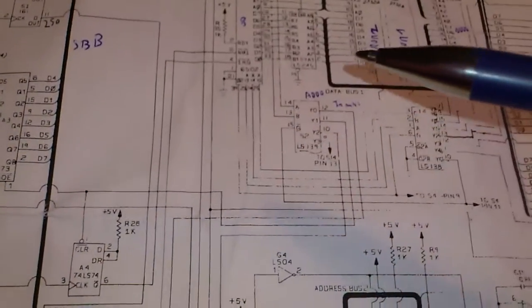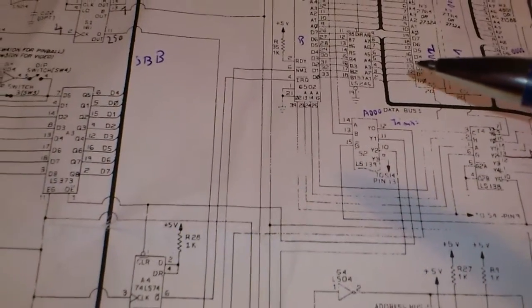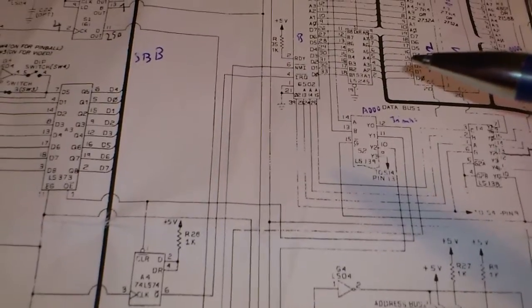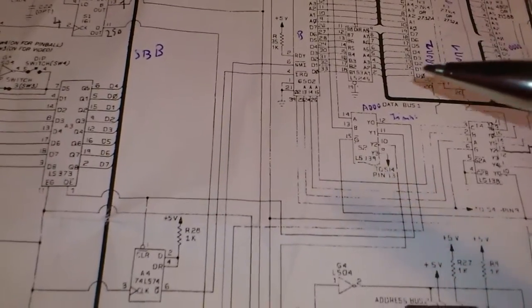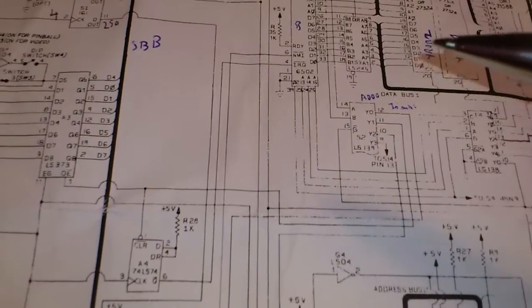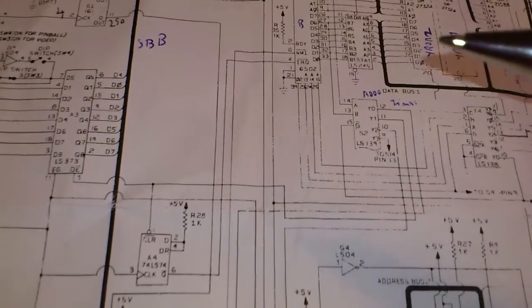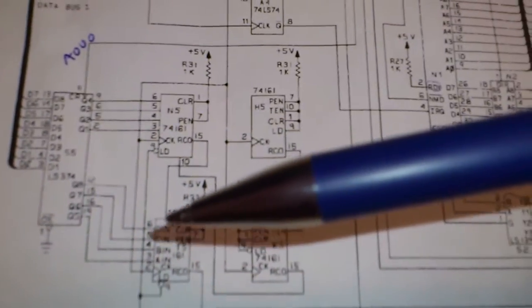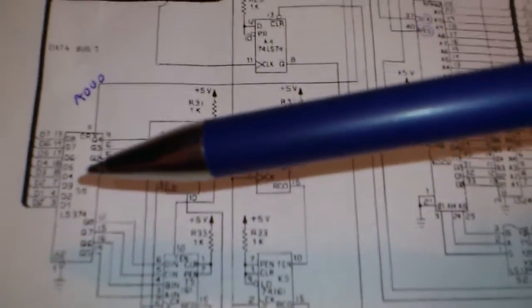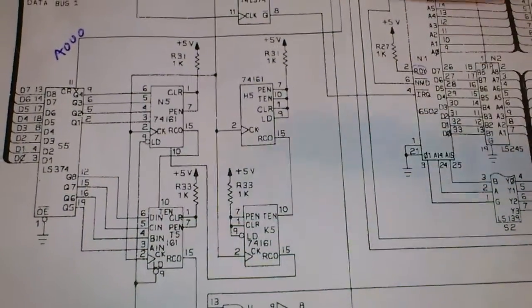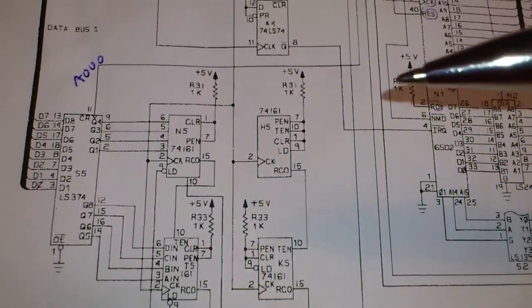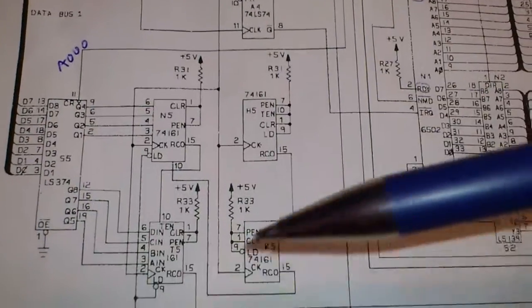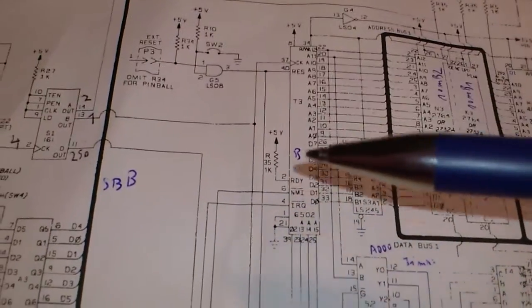So when the CPU is, for example, sending out a given tone to the programmable sound generator, it has to do this with a given beat or a given cycle period. And that's what a rhythm is, maybe I should call it a rhythm. Yeah, this is then generated by the timing logic by always, on an overrun, loading a new value in from the CPU and, on elapsing, giving it a non-maskable interrupt. So that's how that portion works, and that's only accounting for the upper CPU for that one here.